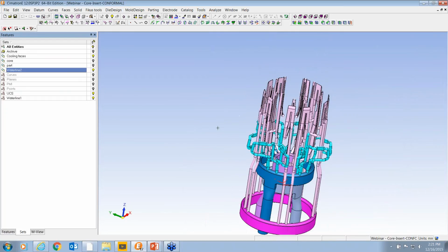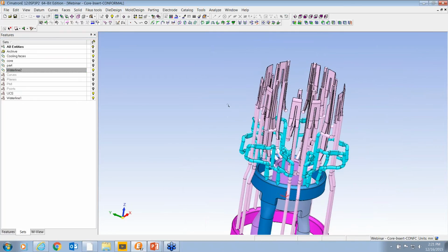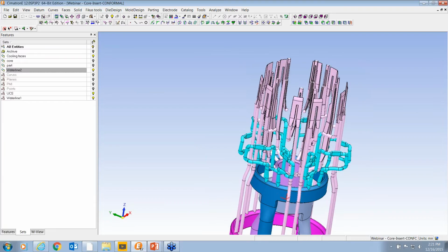Understanding that helps us to see that probably we're going to have to push that water in at a quicker rate in the purple rather than the blue. The idea of uniform, again, we want to get the heat out all at the same time. So that's a factor to consider when we start to see slowdowns or the distance in the total linear distance of the water line being different from circuit to circuit.